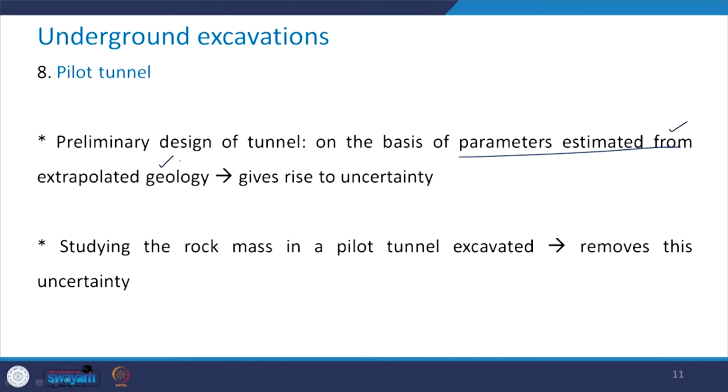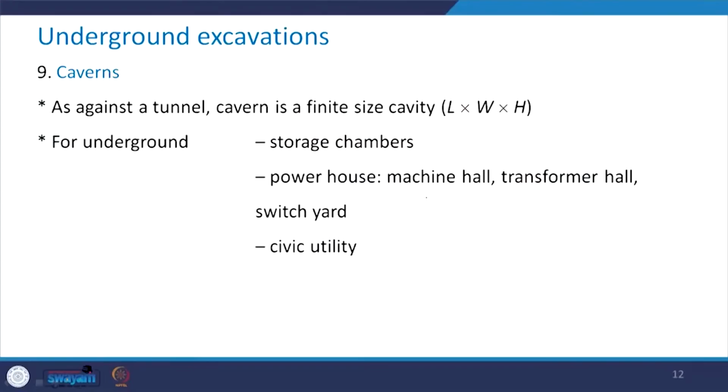Studying the rock mass in an excavated pilot tunnel removes all this uncertainty, and therefore this pilot tunnel, in cases where it is really not possible to go for rock exploration up to that depth, is very useful. The next category is the caverns.